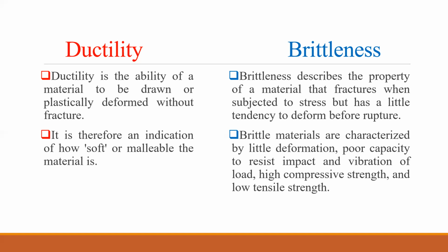So in a broader view, the ductile material will undergo plastic deformation without fracture, and the brittle material does not undergo plastic deformation, or it has less tendency to deform before fracture. If we apply load, the material has to fracture at the end. The material will fail at the end. But before fracturing, there will be a change in shape, or a change in dimension of the material.